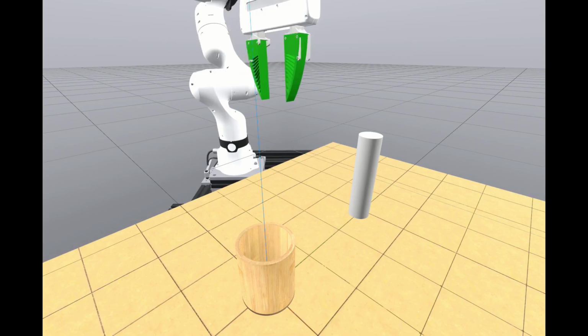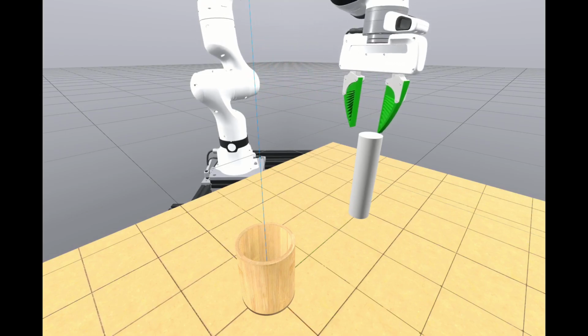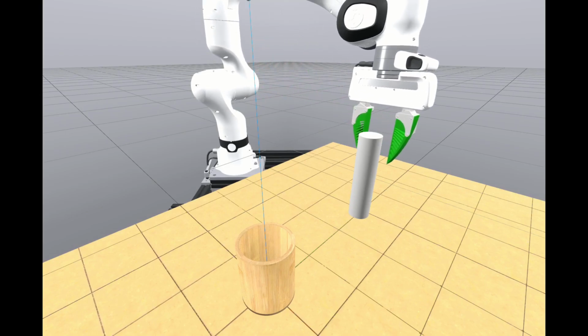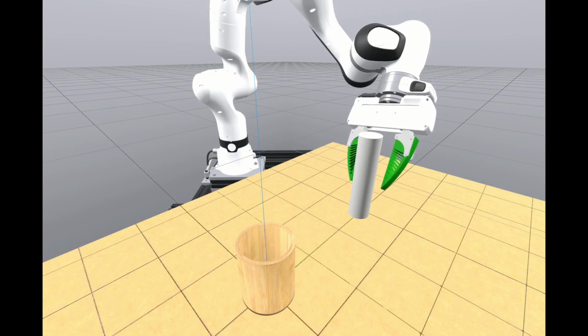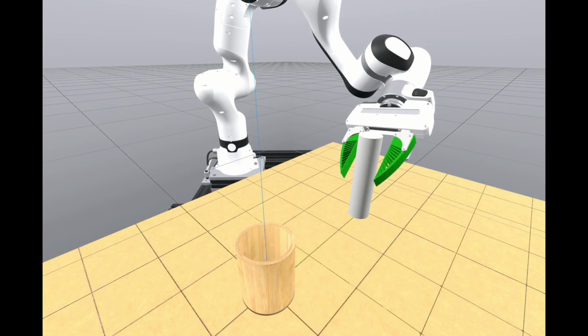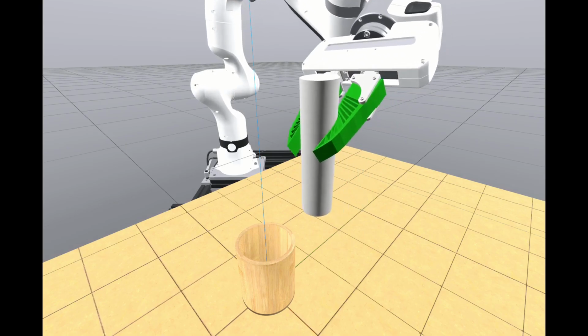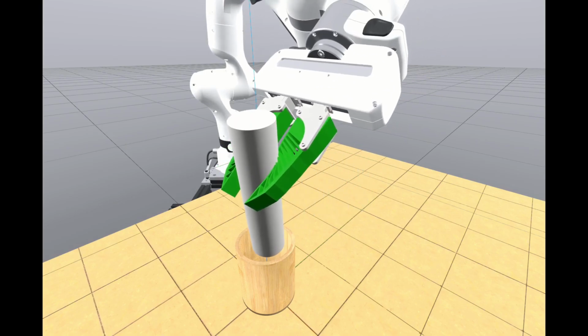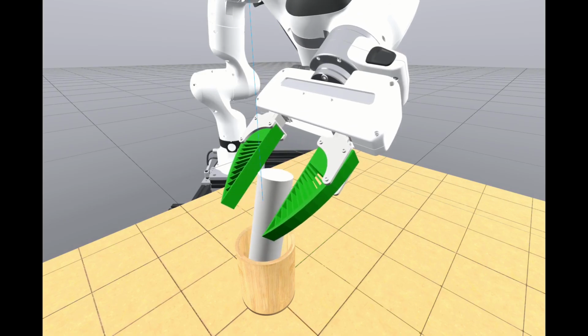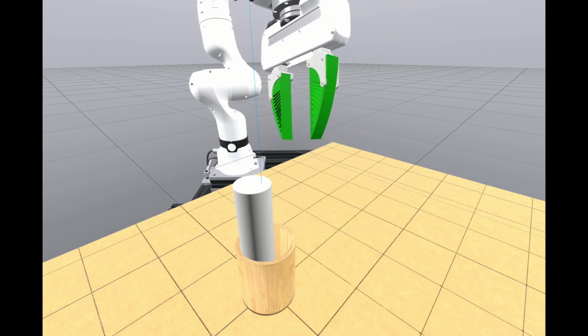Our method naturally extends to supporting frictional contact with deformable bodies. Here, we simulate deformable Fin Ray gripper fingers on a Panda arm in a peg-and-hole task. The robot, teleoperated with a 6 degree of freedom space mouse, completes the task using differential inverse kinematics and a 10 millisecond time step, successfully inserting a rigid peg into a fixed holder.